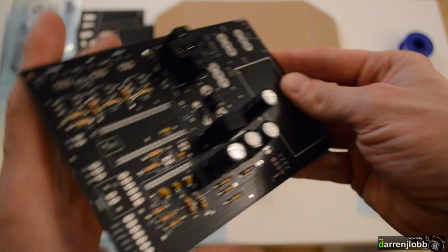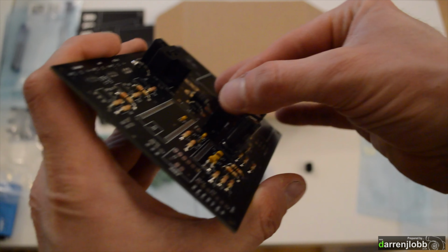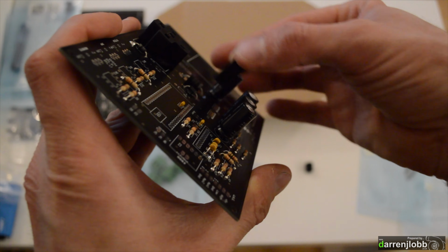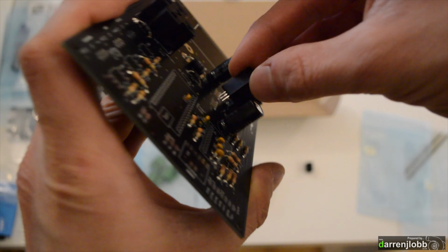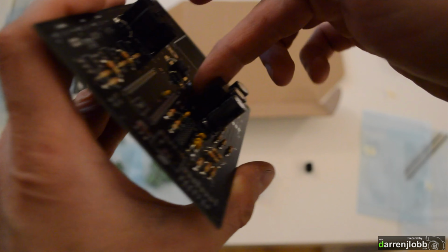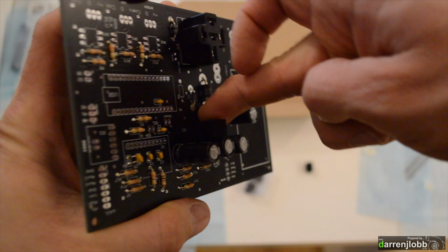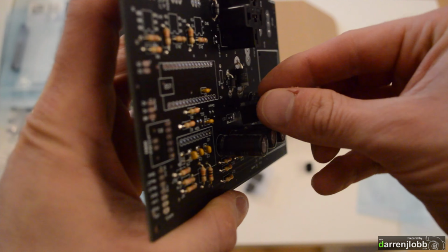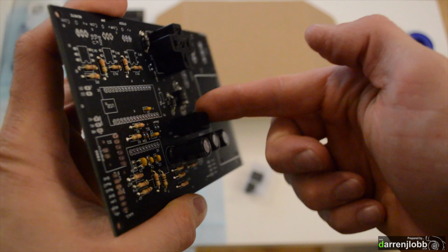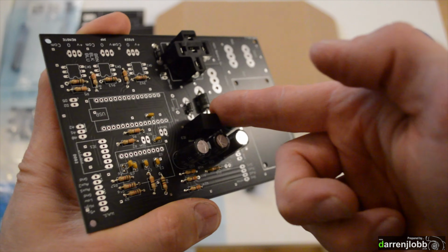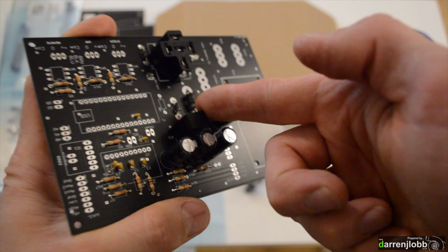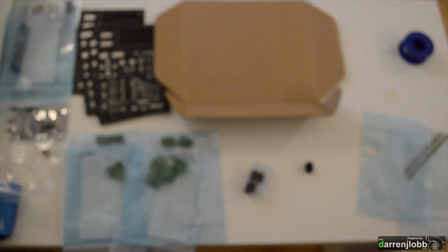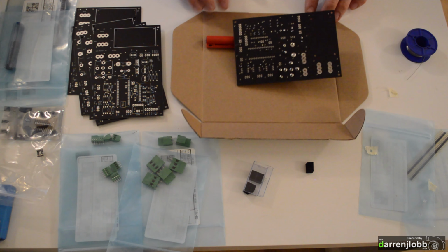The markings aren't very clear on these, but you want to orientate these regulators so they sit about halfway between the cap and those diodes. If you put them the wrong way round and slot them in, they basically touch the cap. That's the wrong way round, so they need to be the other way round. Then you'll see that they sit halfway in between all the other components. They sort of look happy in that position. If you look at the PCB, you've got the white line. You want to put the side that the terminals are on closest to that side on the component. Just using the pen there to prop that item in.